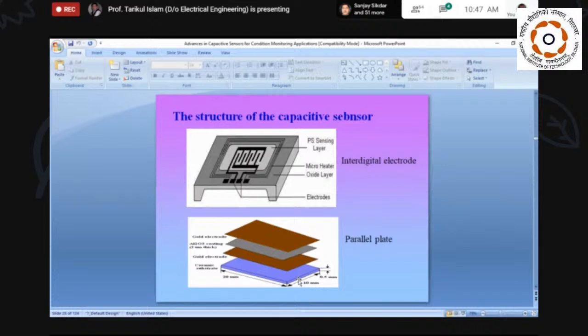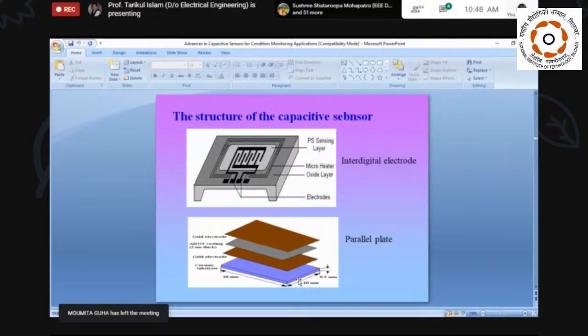It is a chemical route where we have the elements of hydroxide and water, by hydrolysis process and peptization. That salt solution is prepared, and then from that solution we make a film on the metal electrode, and then that metal electrode and metal oxide film is heated at 450 or 500 degrees centigrade for 1 hour or 3 hours.